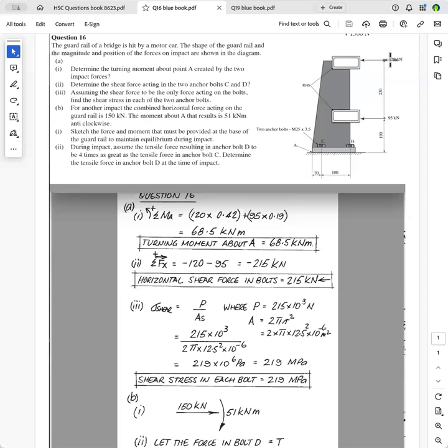So we've got this force here, and we've got to find the perpendicular distance of this force along that line of action to that point there. So you look around and you see you've got a perpendicular distance here. You've got to add 230 to 190 because you've got to go back to the pivot point. That's the lever arm of that force about that point to provide that moment or that torque.